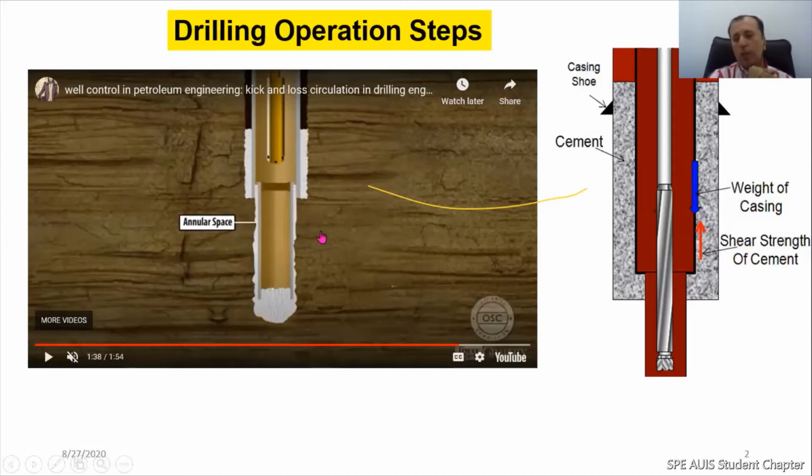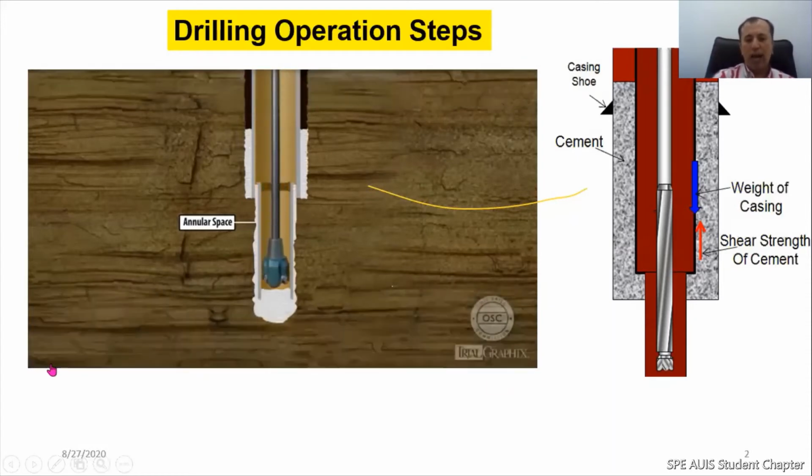In civil engineering, we are looking for a quick set for the cement, but here we are looking for a slow setting time for the cement until the process is finished. Now I have set up the casing. Last part, I'm gonna remove the cement from the ground to be able to take oil and gas from the voids.